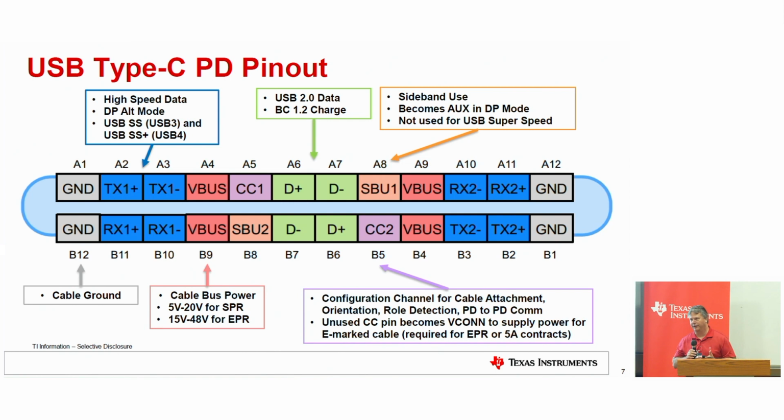If you're talking EPR cable, 48 volt up to 5 amp, they're already factoring in the wire size for the voltage drop. The USB PD spec defines an upper and a lower limit for voltage, and that factors in across the cable, from host side to device side.